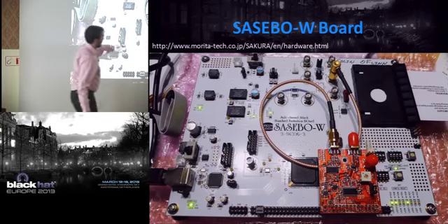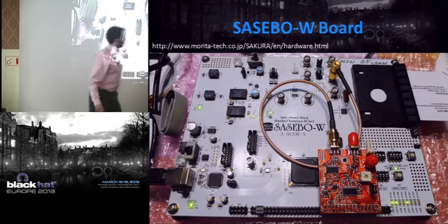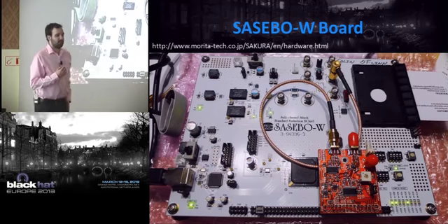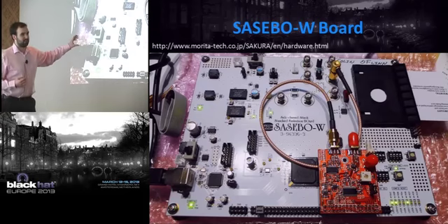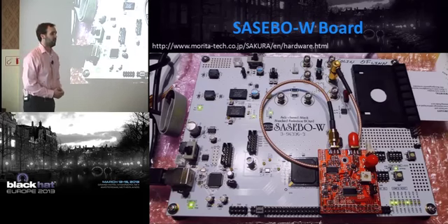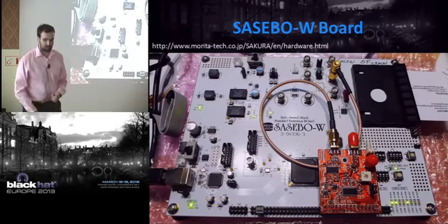But you can use that ADC platform I was showing you earlier, plug it right onto the board. It has a reader for smart cards. It has quite a large FPGA for doing your own processing. So you can do some cool stuff, like say you wanted to do the attack in real time. You put the card in, you're doing the attack in hardware. This board is a good tool for that.